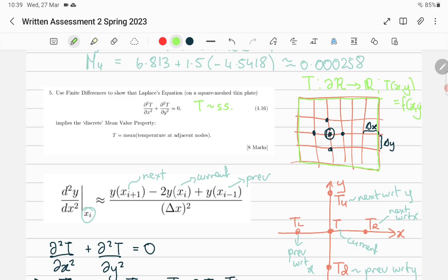So you do know what's going on in the boundaries. And then the question is, for that, everything else is insulated, so the top and the bottom is insulated. So if you imagine setting your plate up with some initial temperature, say 0, and putting it in contact with these boundary temperatures, these heat sources and sinks, and allowing enough time, it'll eventually reach equilibrium at steady state, and the steady state temperature will satisfy this partial differential equation, Laplace's equation.